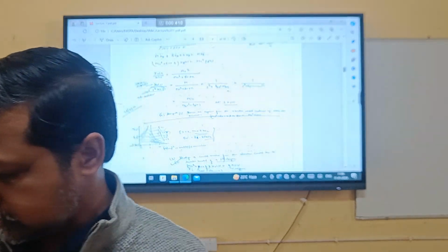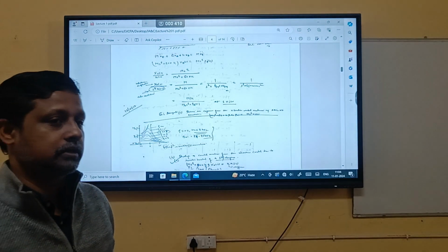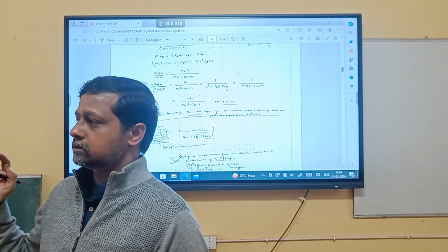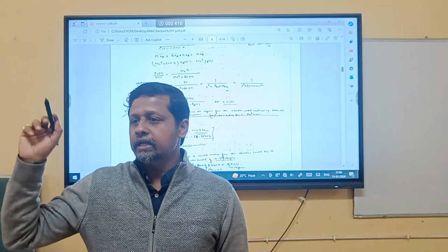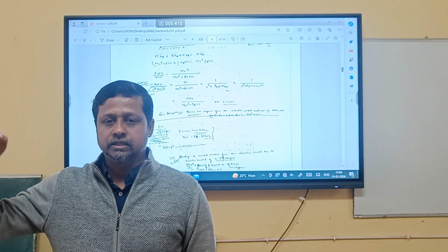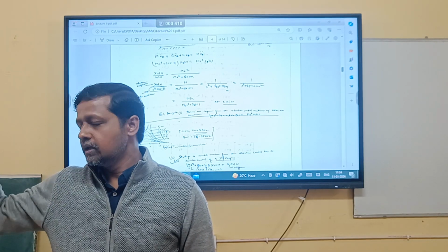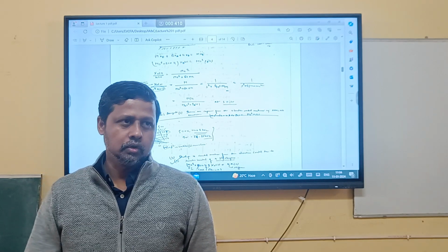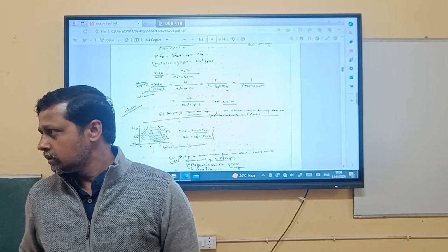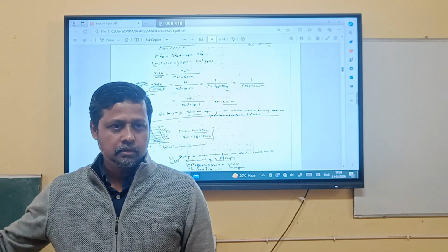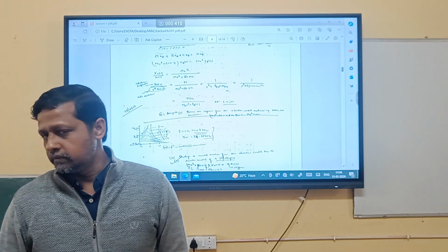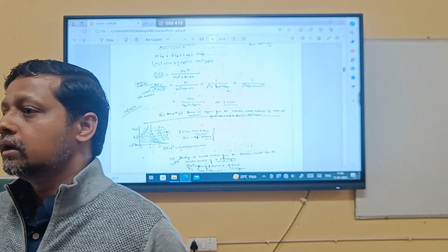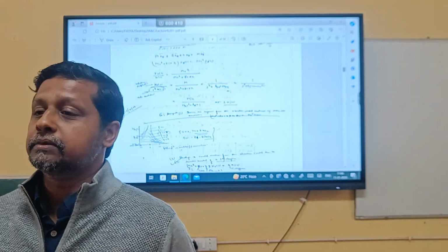Remember, this is one of the real life scenarios of the case study, and these IC numbers you can check. There are two options available. One is the Analog Devices ADXL series, ADXL 150, 210, or ADXL 250 or ADXL 311, where the highest digit indicates in how many dimensions you can measure the acceleration at the same time.